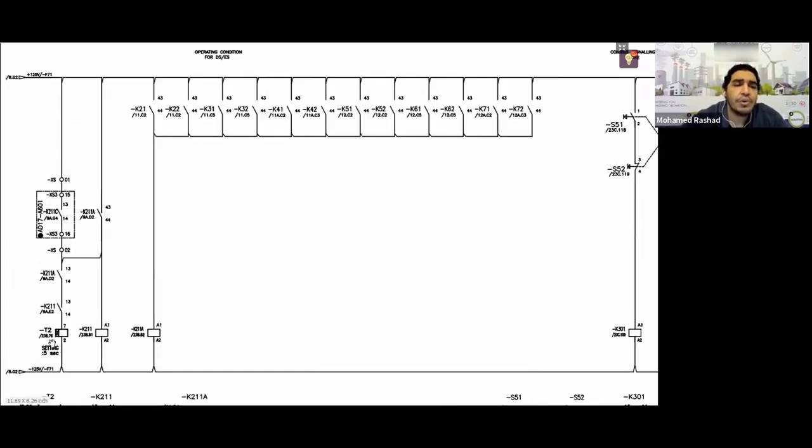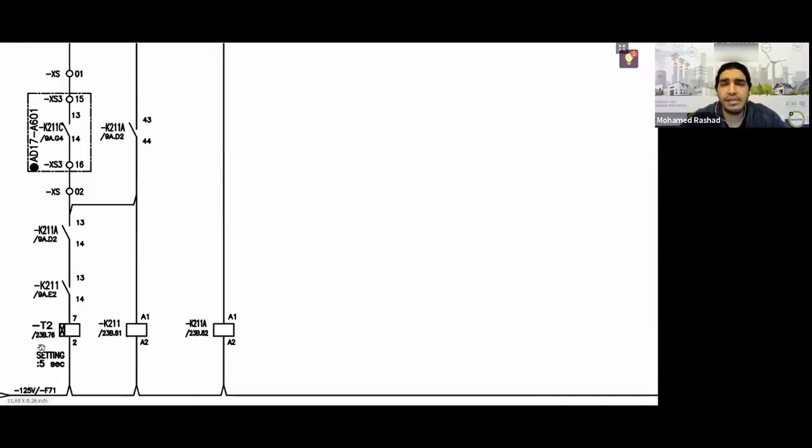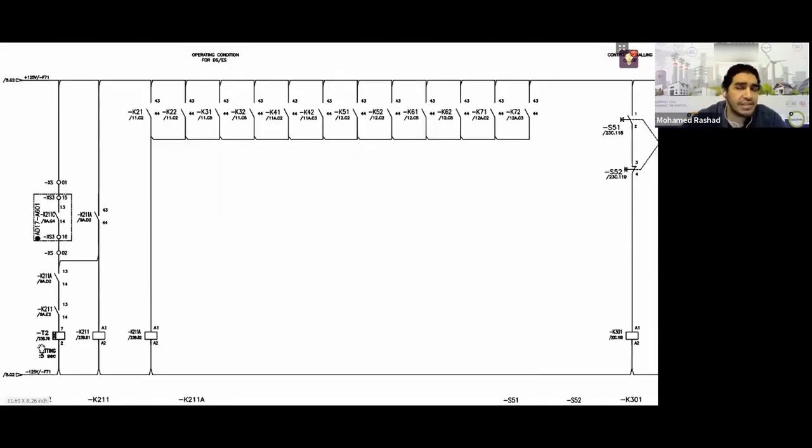All right, great. So the issue isn't about how it's done. It's not like a book. He went here and brought a timer. Okay, the timer named T2 is an on-delay timer. What does an on-delay timer mean? It means that when I supply it with power, it starts counting the time. And then after the time ends, it changes the state of its contact. So how will this happen? This will happen quite simply.